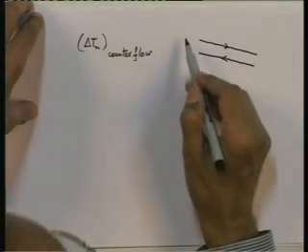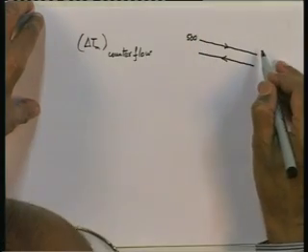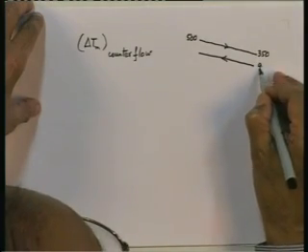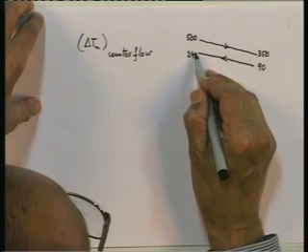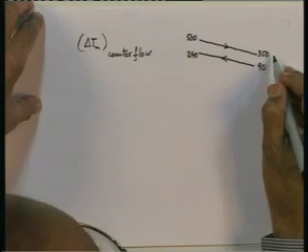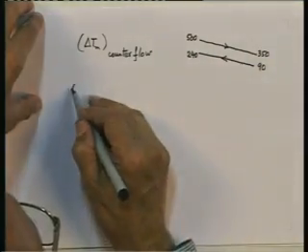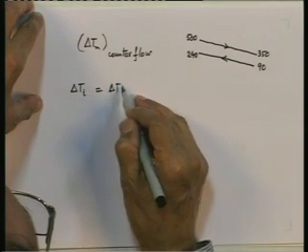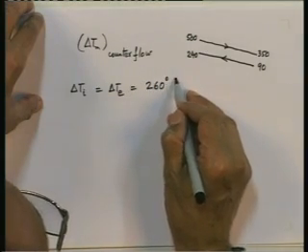So, we are going to have 500 here, hot side fluid entering temperature, 350 leaving, entering T c i 90, leaving T c e 240, and we will get the value of delta T i and delta T e, both in this case will be 260 degrees centigrade.